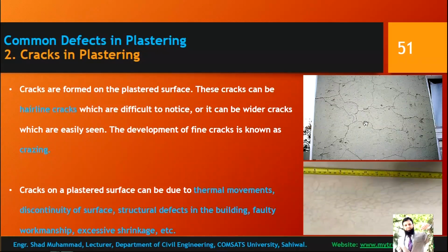We will study in future that due to earthquakes there are some visible, very separated cracks having bigger width, and those are something to be worried about. Otherwise these hairline cracks and crazing are not to be worried about. But these types of cracks do affect the serviceability of the structure.